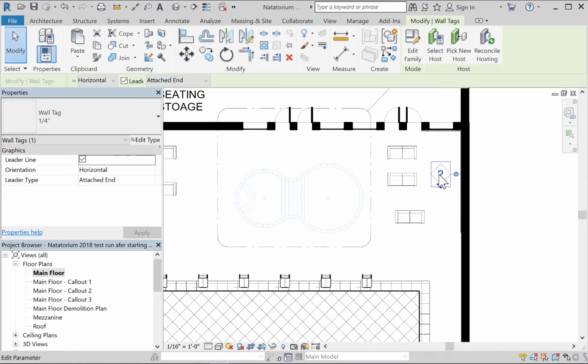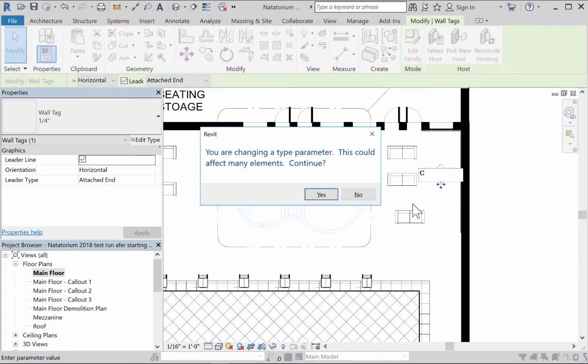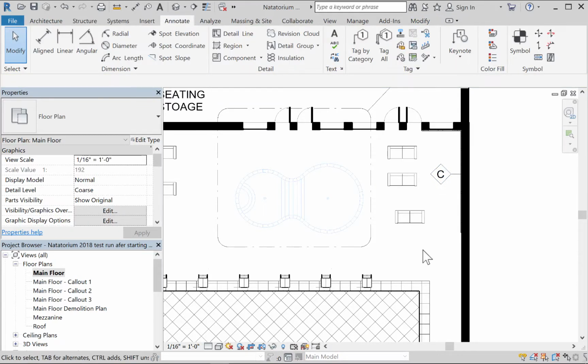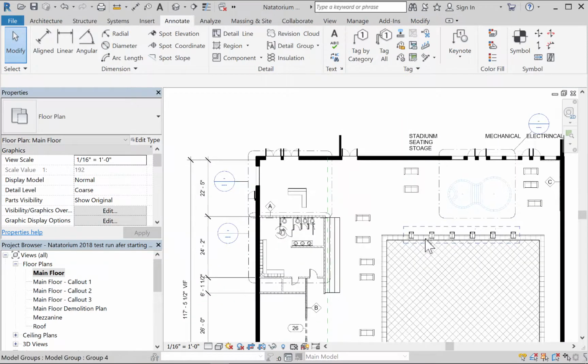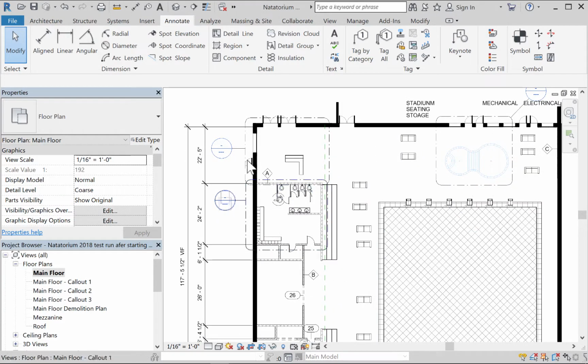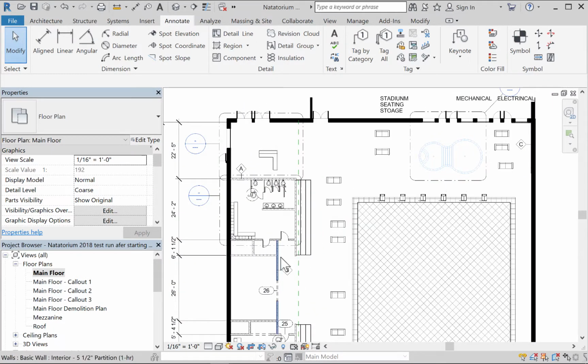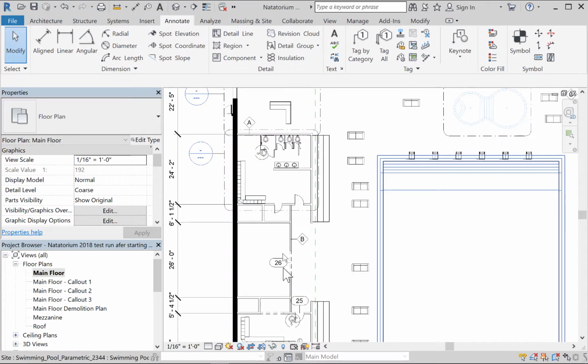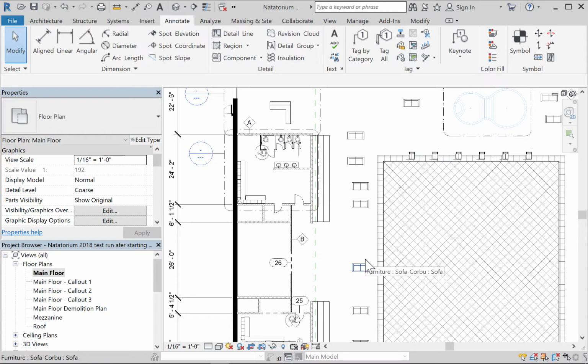Some offices are going to have their own system, like all of your standard interior metal stud partitions are going to be A, or they'll be M for metal stud. So follow whatever your office does. That is basically it to get you through to the start of DD, developing this floor plan, keying in where you're going to have large enlarged sections of plan, and then tagging everything, identifying all the pieces.